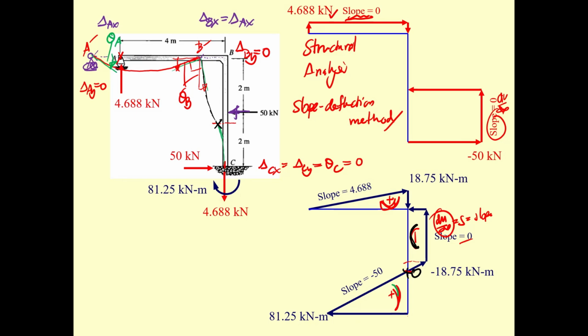Now, Ajahn would like you to think, if this structure is an RC structure, how should you reinforce this structure? Now, do the same thing as before, put the frame as this one, and then this is going to be the fixed end. This is going to be the roller. Most of the time you run the steel for the beam along its length in order to hold the stirrup and have the hook in order to tie the reinforcement close to the concrete.